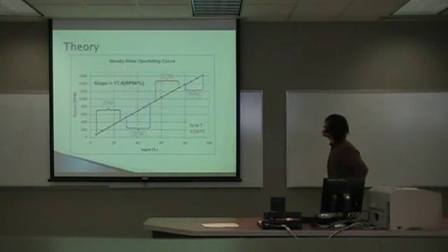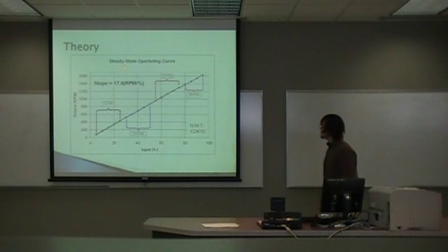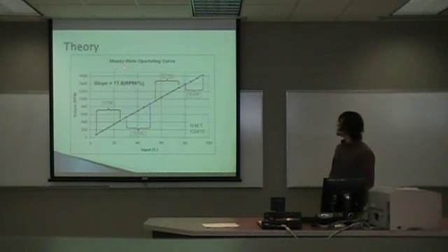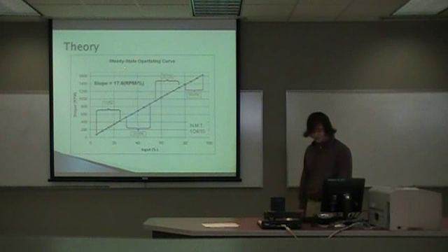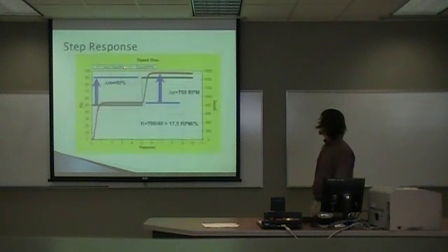This is our wonderful steady state operating curve. As you can tell from the testing range of 5% to 95%, it's completely straight. There's nothing too awesome about it. It's the same way going down as well. And our slope was 17.6 RPMs per percent.